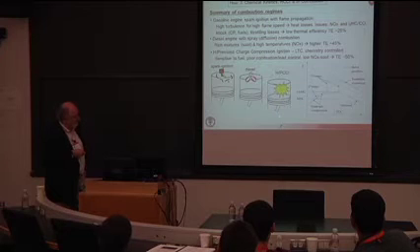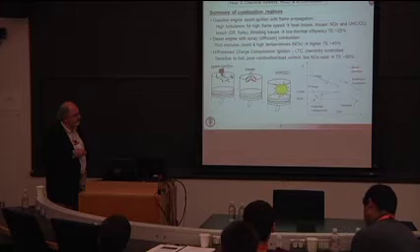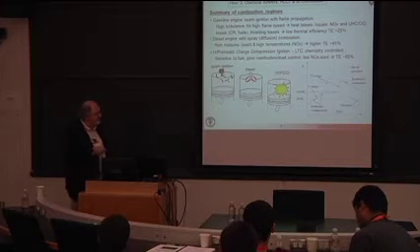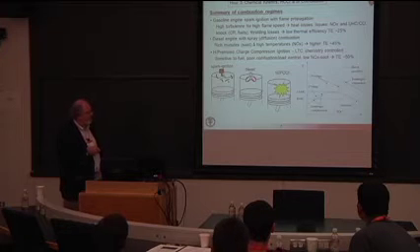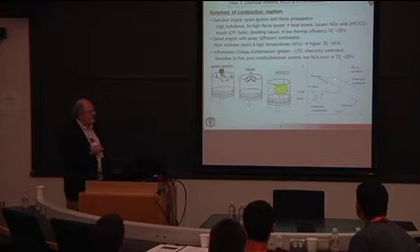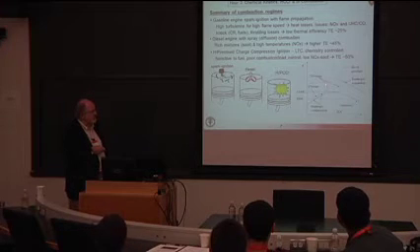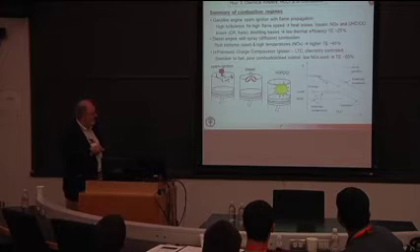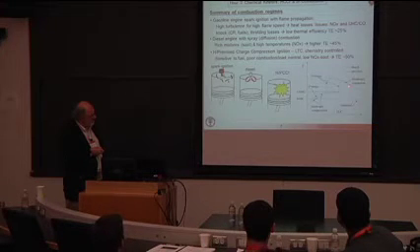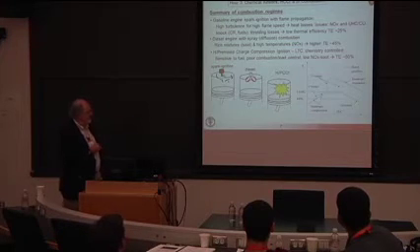I have my compression process, and then because for certain fuels, such as diesel, it's actually a 2-stage ignition process, I have some heat release, and then it sits and cooks some more. And then I get a 2nd stage combustion. But because of this initial heat release, the 2nd stage combustion occurs much earlier than it does for a fuel that has only single-stage combustion, like gasoline. So again, depending on what type of fuel I use, my combustion phasing can be completely different, which leads to this fuel sensitivity.